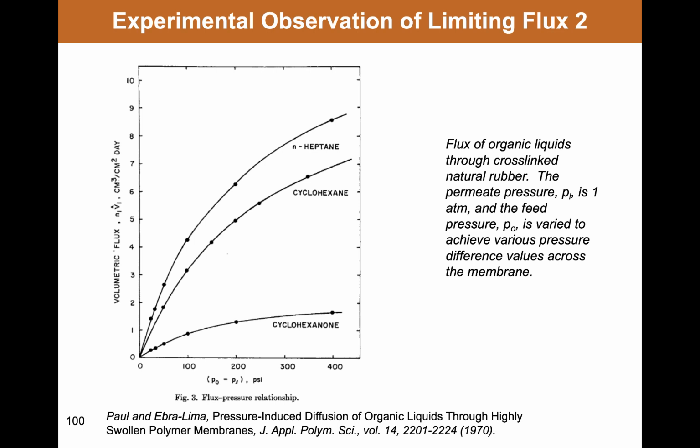However, and results like the ones shown here are being reported in the literature, there has been some confusion in this literature, even very recently, where people have attributed these sorts of flux versus pressure profiles to what they call compaction of the membrane. They're imagining that the membrane is somehow compacted, and often the membranes used in this case have a porous support, and they're imagining that there would be resistance from the porous support, when in fact what they're seeing is a phenomenon that has been widely reported in the literature, but almost 50 years ago.